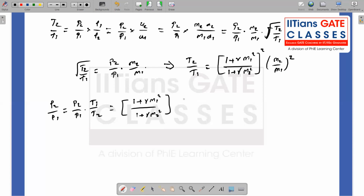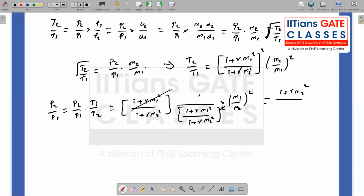If I use that one, I get 1 divided by 1 plus gamma M1 square divided by 1 plus gamma M2 square, multiplying M1 by M2, sorry, inverse, right? M1 by M2 whole square. So the 1 and 1 terms get cancelled. So it gives you 1 plus gamma M2 square divided by 1 plus gamma M1 square times M1 by M2 whole square.